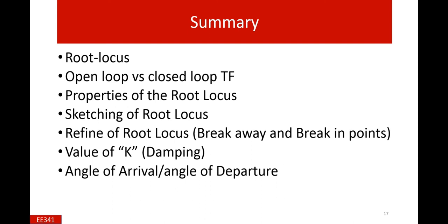And similarly, we find the parameter k, and there are a lot of discussions like the stability factor, and we develop the Routh table, and from the Routh table we find that at some specific value of k, the system shows oscillating behavior. For stability, k should be less than that critical value. If we change the value of k greater than that value, then it is an unstable system.